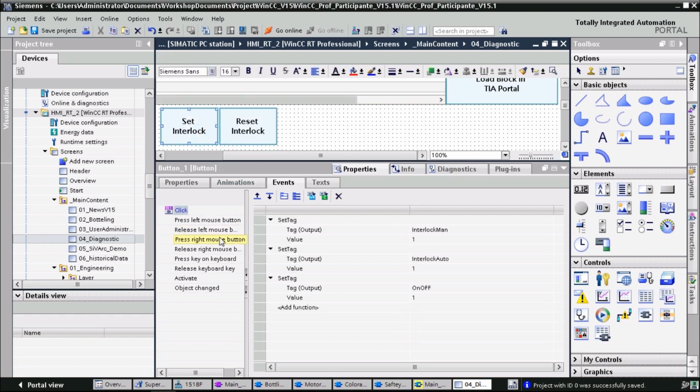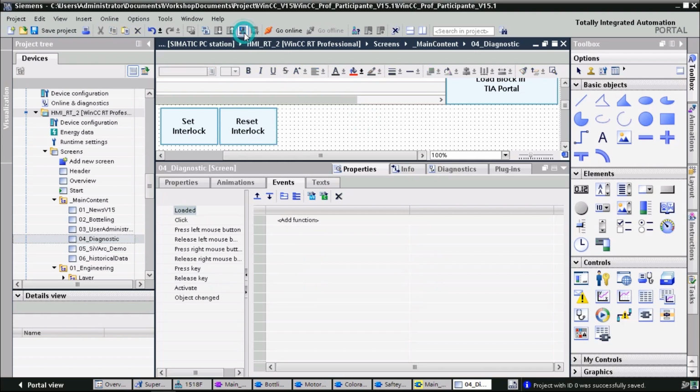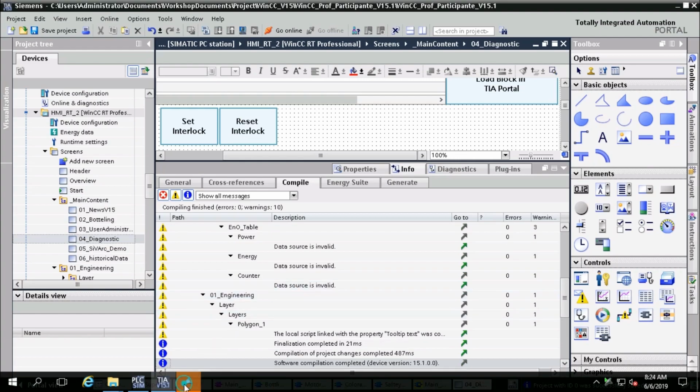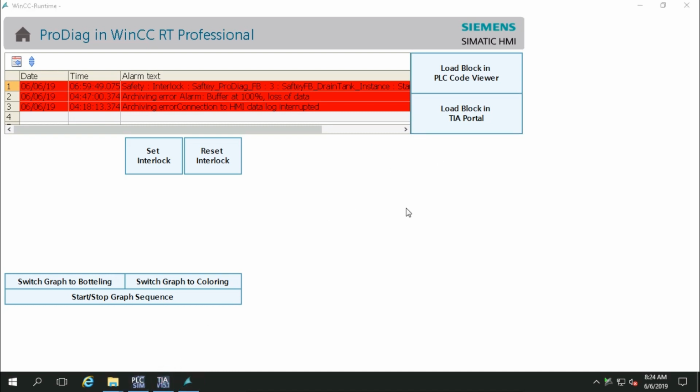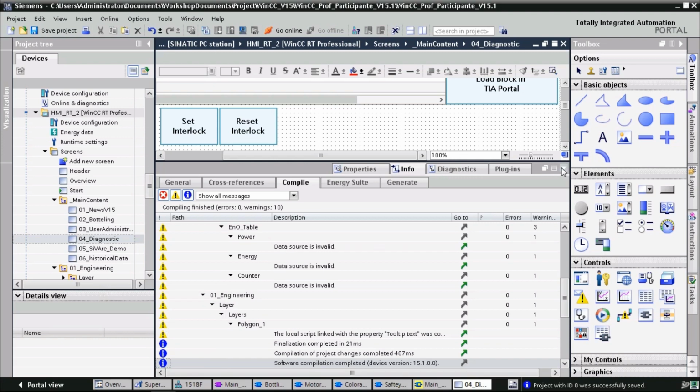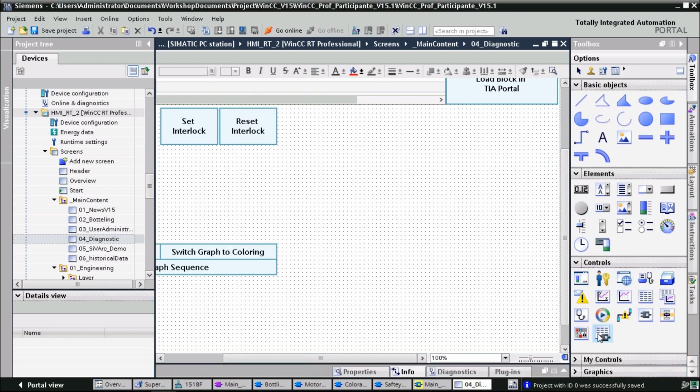Name of the PLC code view, so this control here, is also PLCCodeView_1, which is the correct name in here. The only thing we need to do is insert the error tag, which I have already pre-configured, in our HMI tags under the folder again ProGuide. You find here error tags. These are internal tags, and I called it error code viewer. So I'm going to choose this tag here.